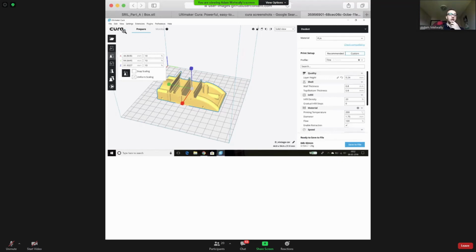But yeah, so Cura is the software that you'd use. It'd be Ultimaker Cura, and you would load in the STL. Then you can move it around the printer depending on whether you want to print it in the middle of the bed, etc. You can mirror it, so you can print multiple parts, rotate it, maybe make it fit if it's not fitting, move it around, etc. So that's what that would look like after you would export it.